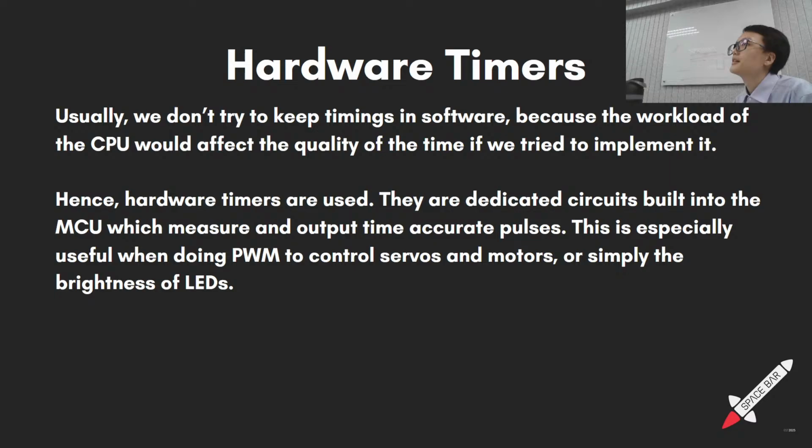So this is like one data line of UART, and basically these are the data bits, from 0 to 8. So you are sending a byte over. A byte is 8 bits, by the way. And with UART, there's always a start bit, and you got 8 data bits.